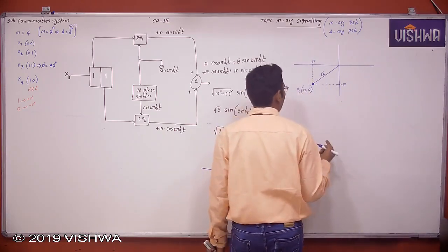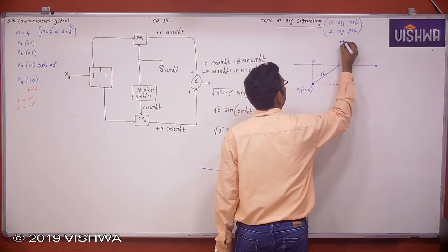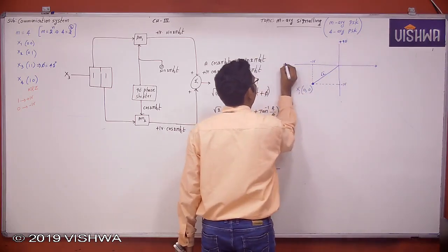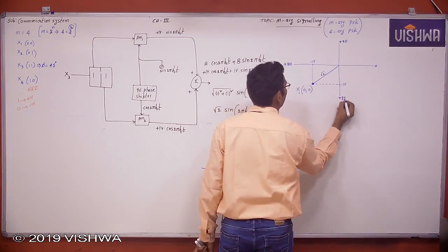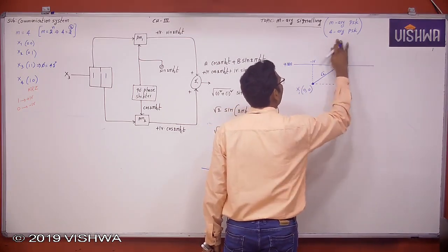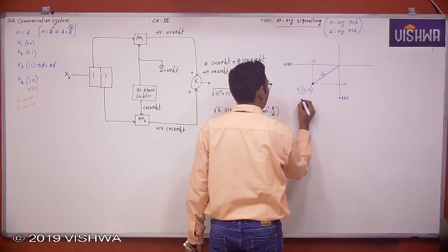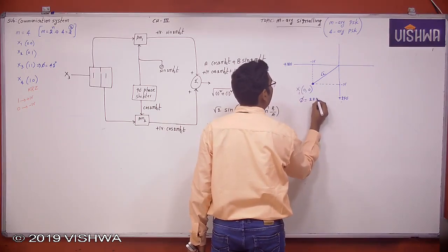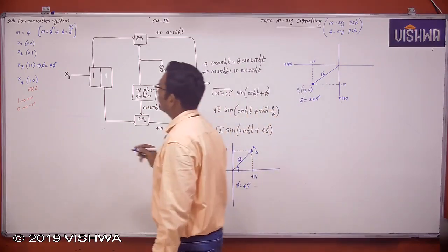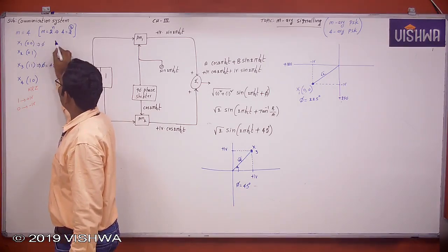You can take positive phases: 0 degrees, plus 90 degrees, plus 180 degrees, plus 270 degrees. Now exactly the middle, between 180 and 270, is the middle one. Therefore the phase produced here is 225 degrees. So the first symbol produces a phase of 225 degrees.